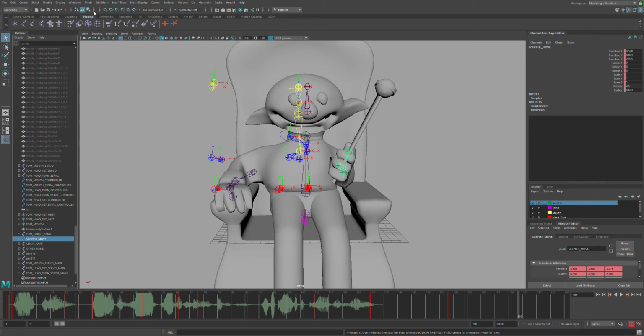Now you need to go onto the same location where you had saved your file for the story time experience, that is the recent file that you saved, which I saved by the name of s1_1. So I'm just going to click on it and select open. As you can see here, the file has been loaded. Now in order to locate the joints, you need to go ahead and click on scan for objects.